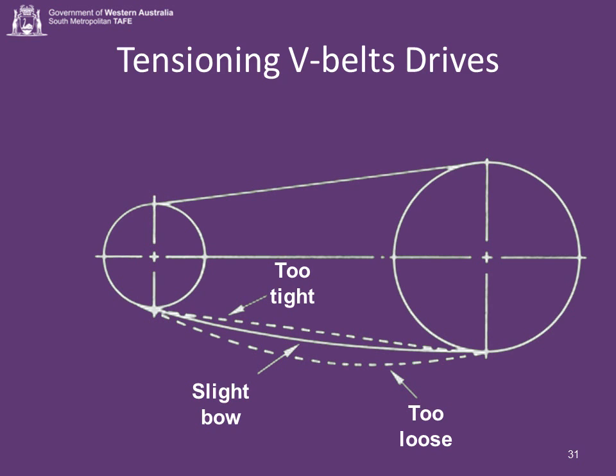The most important factor in the operation of V-belt drives is proper belt tensioning. Belt tension must be sufficient to overcome slipping under maximum load. To increase total tension, merely increase the center distance. Before attempting to tension any drive, it is important that the sheaves be properly installed and aligned. If a V-belt slips, it is too loose. Add to the tension by increasing the center distance. Never apply belt dressing.